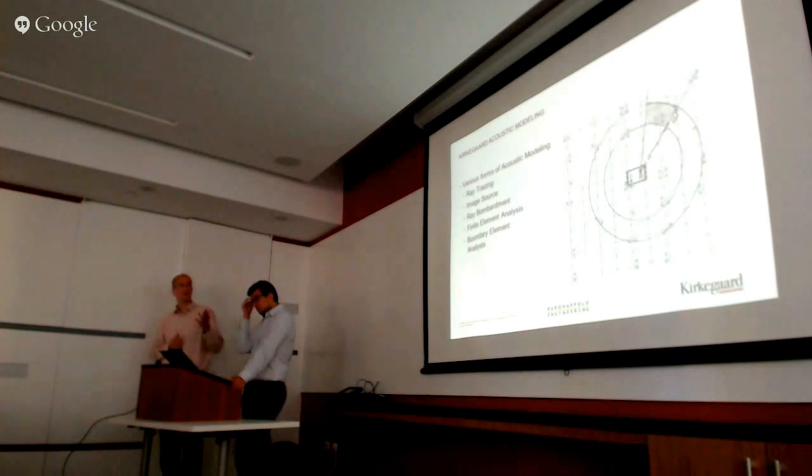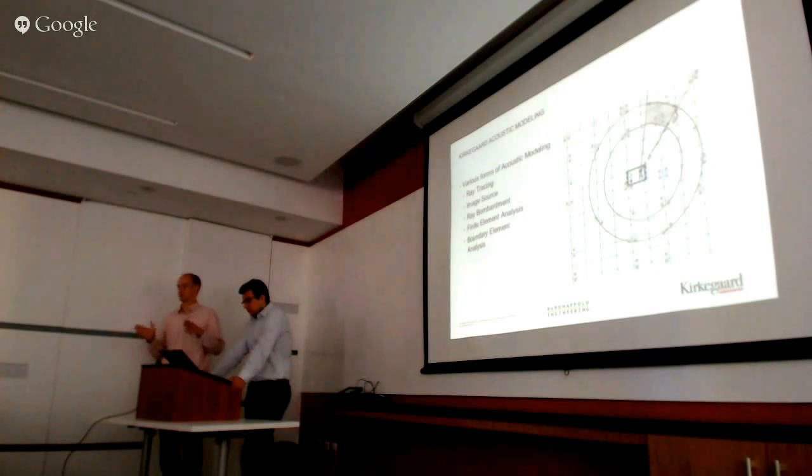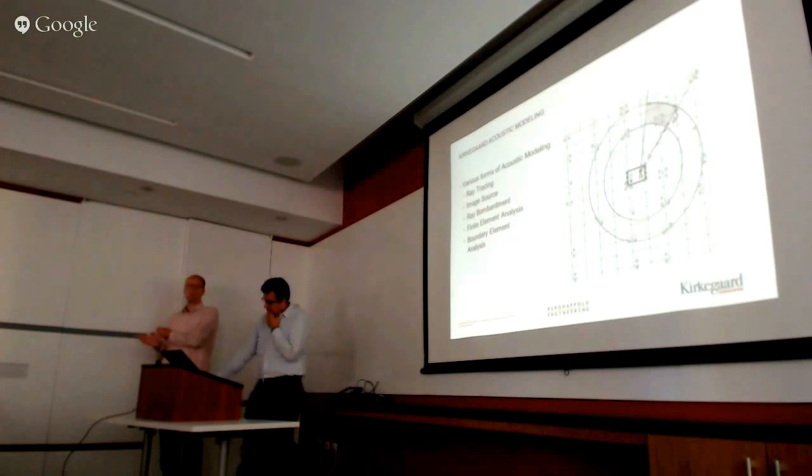The image source solution is a great solution in terms of the computational accuracy of it. What it does is it basically treats each of the planar surfaces as a mirror, and instead of looking at geometrically what reflects off of that surface as it goes around the room, it uses it as a mirror and then creates an imaginary source that comes in at a later time.